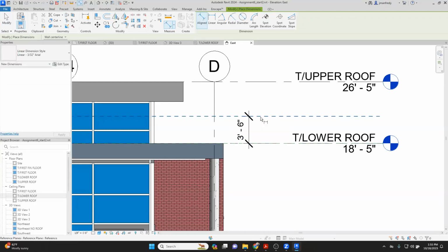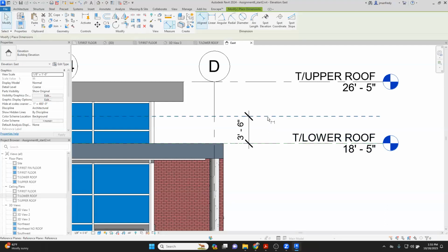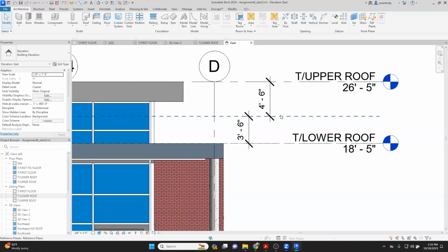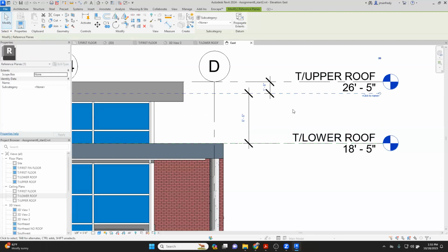Cut through the building here, look down on top of the floor, show me what you see. The reflective ceiling plan view range cuts through here, looks up to here, and shows you everything happening between this and this as a reflection on the floor. So obviously if I cut through the roof, I'm looking between here and here, and I see a bunch of nothing except for inside the roof.